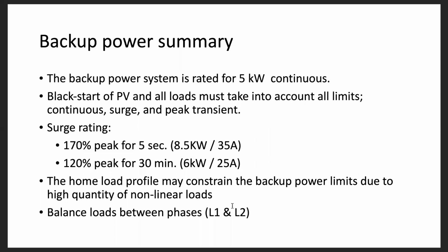And of course, you want to balance your loads between the phases, L1 and L2, on that backup loads panel. For example, if you've got a refrigerator and a microwave, if it's possible to put them on opposite phases, then there's going to be a lot less chance that both of them are cycling at the same time on one phase and exceed the surge rating. And again, it's really important to measure what those characteristics are.